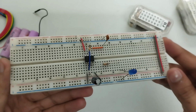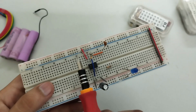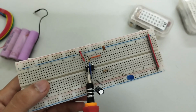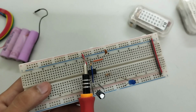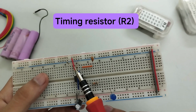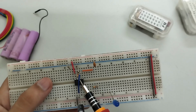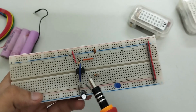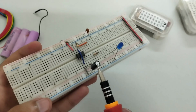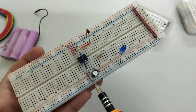So look at the circuit connection for the astable mode of 555 IC, and let me tell you all the connections one by one. This first resistor is the current limiting resistor, which is connected across the VCC and the discharge pin, right? And the value I'm choosing is 2 kilo ohm. You can choose any other value. The second resistor is the timing resistor, which is the main one in this entire circuit. So it is connected across the discharge pin and threshold pin. In the astable mode, we usually short circuit the pin number 6 and pin number 2, okay, using this wire. And this electrolytic capacitor is connected across the trigger pin, pin number 2, and the ground.